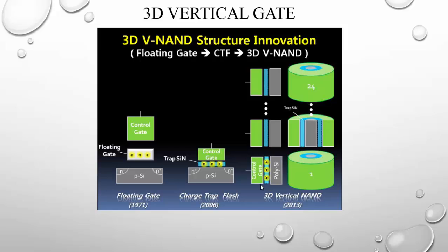So reduced oxide stress and lower sensitivity to single point defects combine to significantly improve overall reliability. Samsung, in its V-NAND rollout last August, claimed that a charge trap provides twice to 10 times the reliability of sub-20 nanometer planar floating gate NAND flash memory. Also, charge traps consume less energy during program and erase, so a 3D NAND based upon a charge trap is likely to be more energy efficient than its floating gate counterpart. This translates to longer battery life.